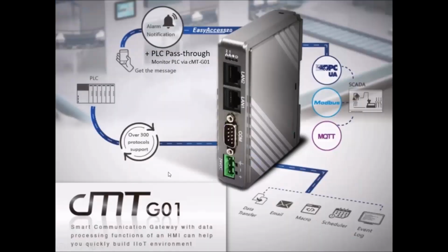So we have cMT-G01, which supports OPC UA server and also client, and Modbus TCP, RTU, client and server, and MQTT client and also server. Okay, so this is a very useful device if you want to integrate into Industry 4.0 or IoT systems.